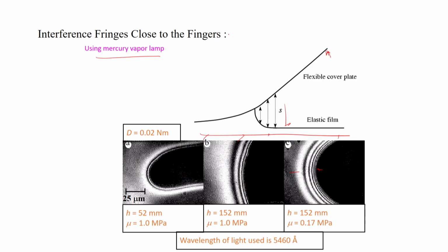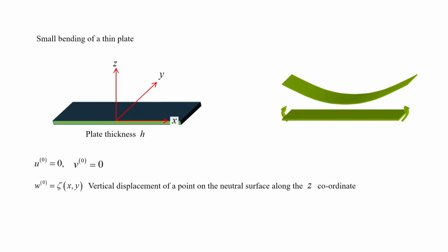In most adhesive tapes, we have a very flexible, very soft backing. So, we do not much worry about the bending energy or the stretching energy stored in this film, but that is not correct, because if you want to do a rigorous analysis, then this bending energy needs to be considered, and particularly if this adherent becomes stiffer rather than soft, the bending energy further increases. Therefore, we need to consider this bending aspect, and that will also give us an idea about the flexural rigidity. So, today I will stop here and I will take up this bending aspect in my next lecture. Thank you.